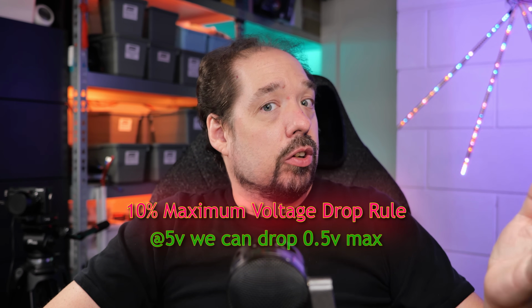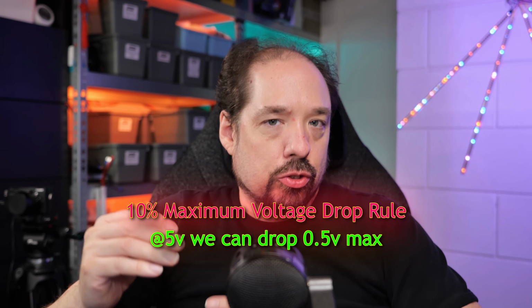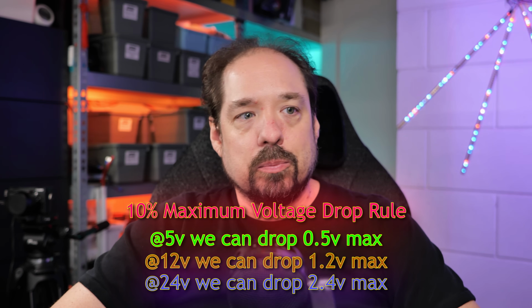With LEDs, for power injection like this, we have a device that needs 5 volt. So if 3 volt comes in, yeah, that's not going to do much. We need 5 volt. We're not down converting at the end anymore. And that's why we need to size up these cables so much, because we can't really afford much voltage drops. If we input 5 volt, we need 5 volt to arrive at the end. Now, we need to have some margin here. So I have a 10% rule. That means at 5 volt, we can drop 0.5 volt. So 4.5 volt, and we're still okay. That's also within specifications of the LEDs and things like that.